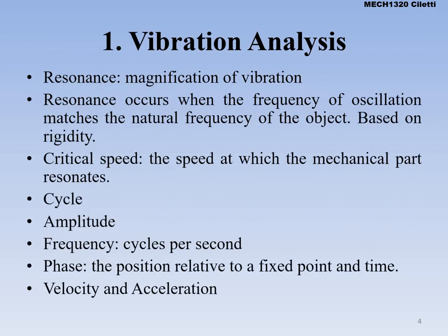So if we step even deeper in, right, we're talking vibration analysis. We're looking at the resonance, okay, the magnification of the vibration, right? Motors operate at a normal frequency or things like that. But if something happens and there's an extra load on the motor, okay, it's not going to move around as fast or things like that. Or something becomes loose and the motor starts to shake, okay, different things like that. So we look for different things like the critical speed, okay? That's the speed at which that mechanical part naturally resonates, okay? And it could go one way or the other from there, but that's the critical speed, okay?